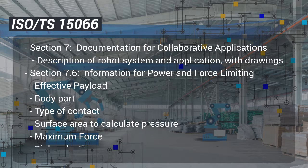Finally, risk reduction measures should be described. These might include reducing the robot's speed when approaching pinch points, wrapping rigid objects with foam, tools that break away at certain forces, and fixtures that are spring-loaded and deflect if an operator is trapped by the robot.